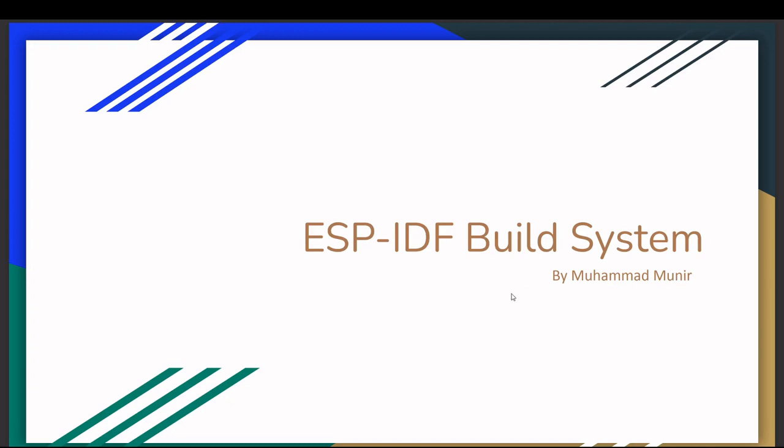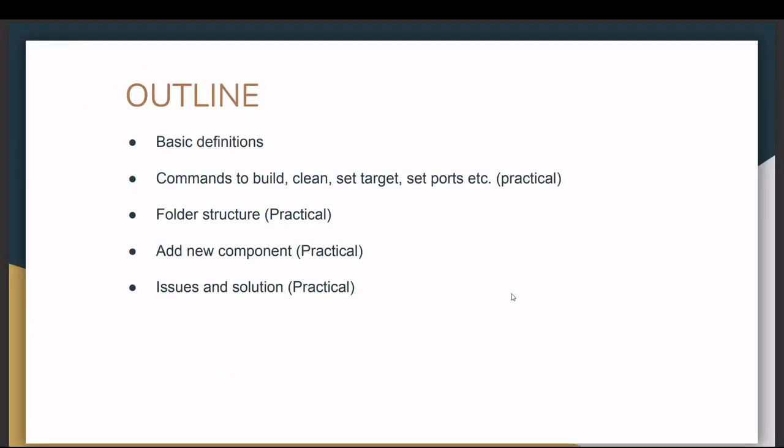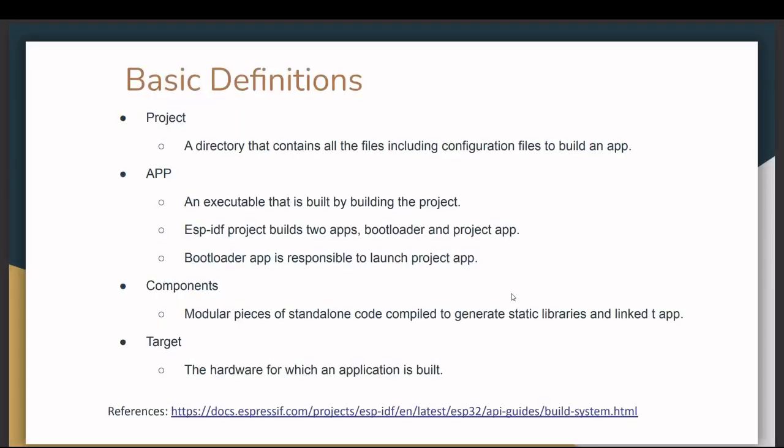In today's video, I will describe the ESP-IDF build system. Here is the outline for today's video. I will give you the basic definitions, and then I will tell you some commands to build, flash, and clean your project by setting the appropriate target and appropriate ports. Then I will tell you what folder structure ESP-IDF follows and how you can add new components into it. And then I will list down some issues and provide their solutions.